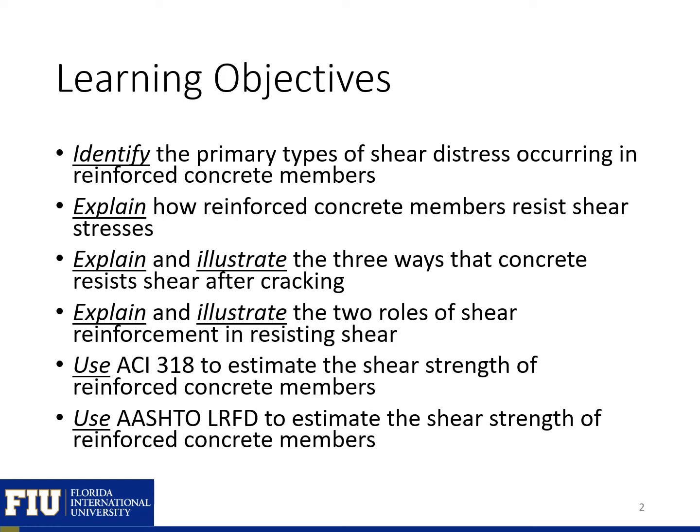We'll see how we can explain how reinforced concrete members resist shear stresses. Explain and illustrate the three ways that concrete resists shear after cracking. Explain and illustrate the two roles of shear reinforcement in resisting shear. And use ACI 318 and AASHTO LRFD to estimate the shear strength of reinforced concrete members.